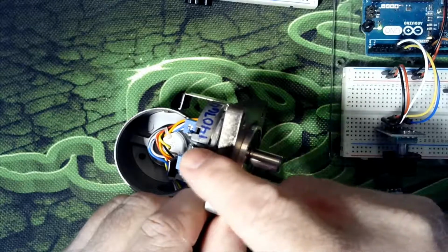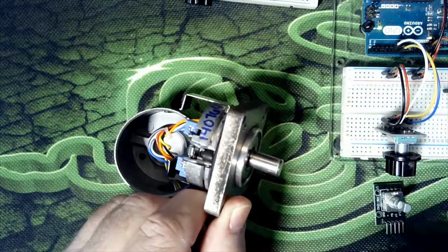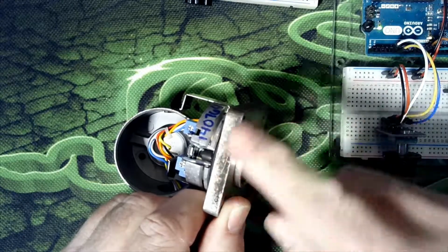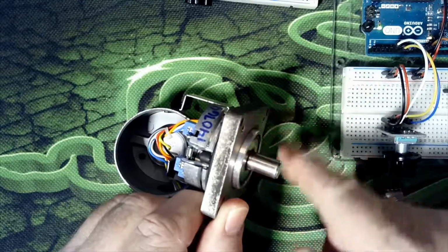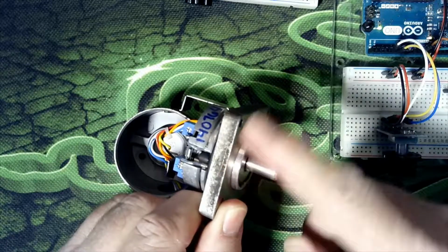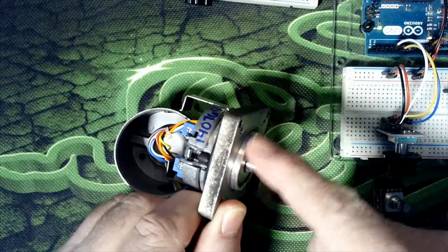And the light passes through and hits the sensors, but it's seen and blocked, just like the slit was on that big plastic wheel, except these are very tiny. And on the outer rings, which are channels A and B, there are 500 holes per revolution. Channel Z has 1 hole per revolution. So it can actually count how many full turns this has made.